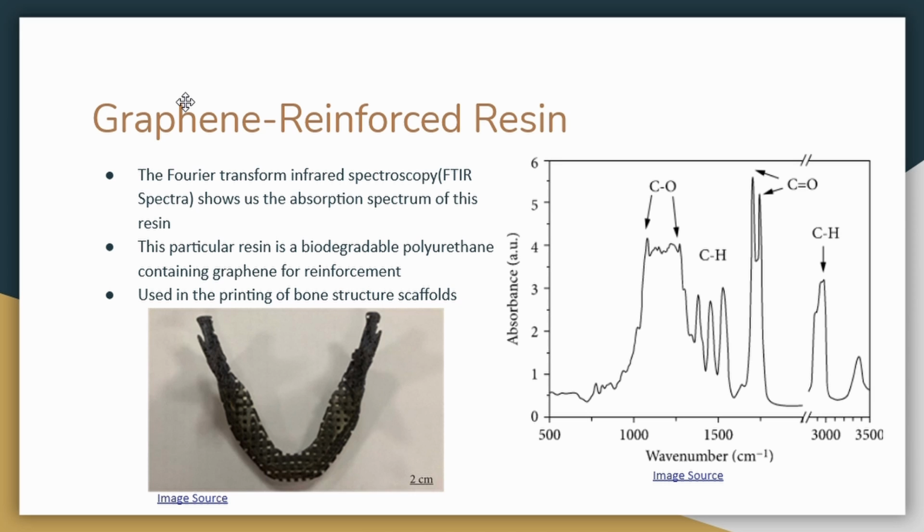The flexural strength and modulus can reach 115 megapascals and 5.8 gigapascals respectively. This is very, very promising for the future of prosthetics because it will give patients a made-to-order experience when it comes to bone replacements. For this particular study, researchers printed jawbones with square architectures like the one pictured, as well as sternums with circle architectures for testing.